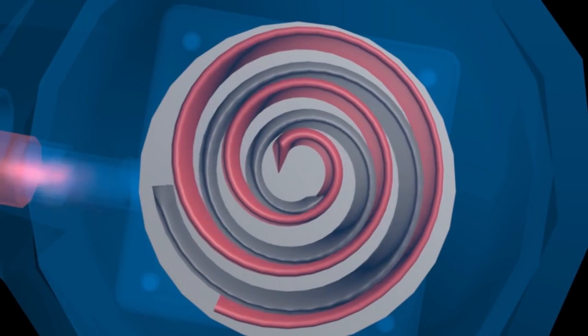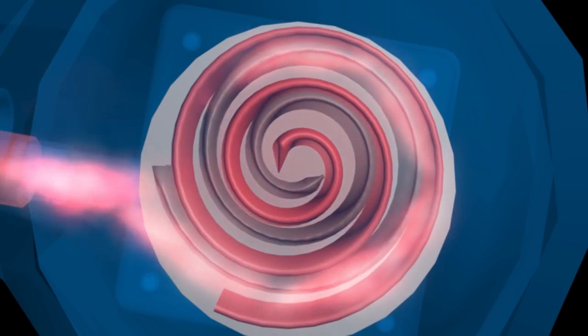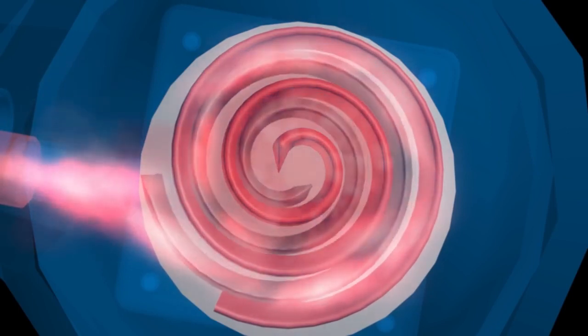Scroll compressor works as follows: gas at low pressure and temperature enters the suction line and goes into the compressor. The low pressure and temperature gas is pressurized by the scroll compressor to high pressure and temperature gas. The high pressure and temperature gas is then passed through the discharge line and goes into the condenser.